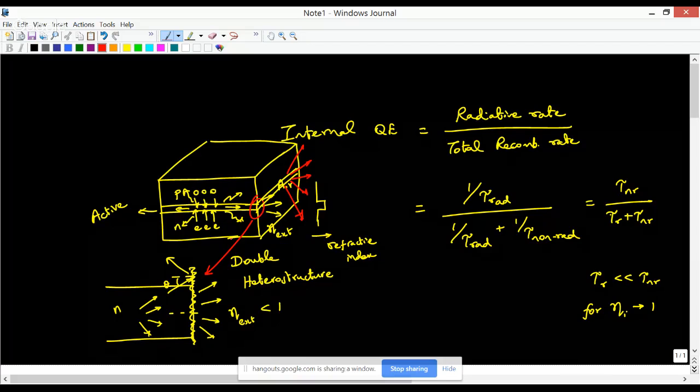Whereas in the horizontal direction, there is not as much confinement that's happening. So in the horizontal direction, it doesn't tend to diverge as much. Okay, so it won't diffract as much. So you will essentially see that the total beam that you get in the far field is actually elliptical in nature.